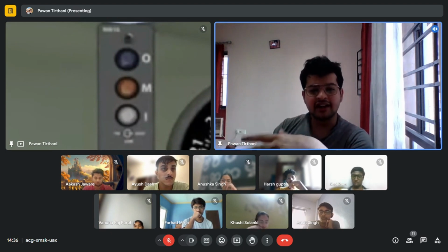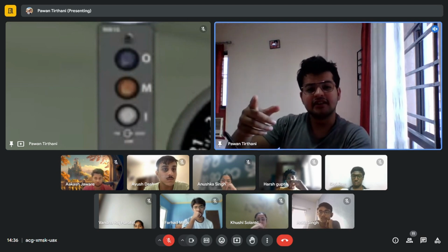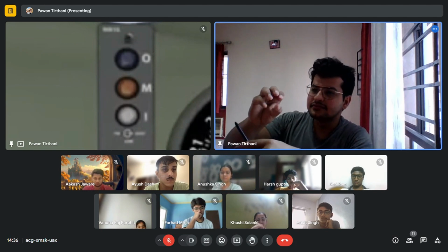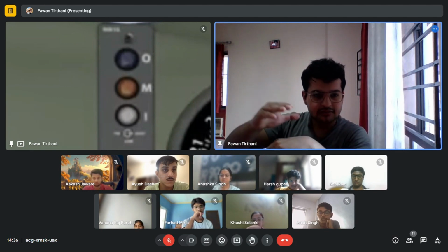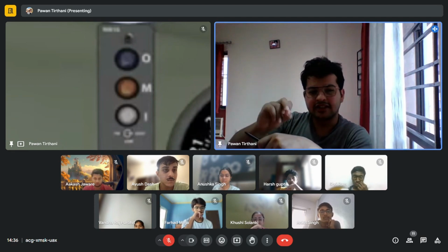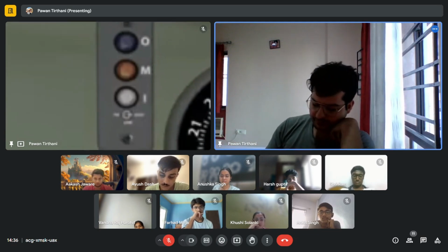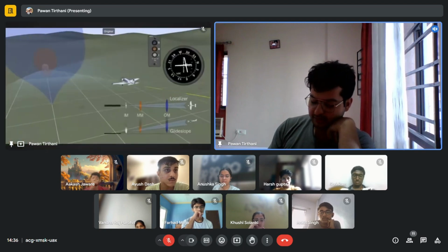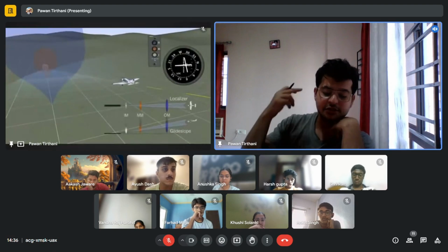तो ब्लू मैंने लिखा दिया, मतलब क्या भाई? ब्लू कलर का एक बल्ब होगा, वो जलेगा. किस हिसाब से जलेगा? आउटर मार्कर इज 2 dashes, तो it will glow like a dash, a long bright light. Okay. But how will a dot? Tick tick tick. एक डॉट वैसे होगा. ओके. यहाँ पे आपको वर्टिकल, यहाँ पे पोजीशन भी दिखा दे रहे हैं कि मिडिल मार्कर एंड मार्कर कितना है. आप बस इन दोनों को देखना, इंडिकेशंस आपको देखने. ओके. एंड लिसन टू इट.